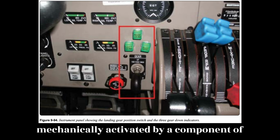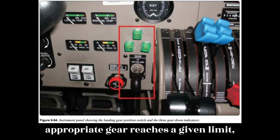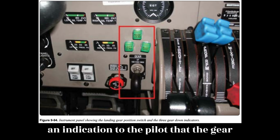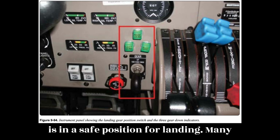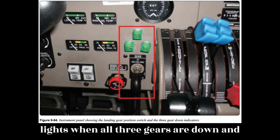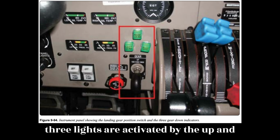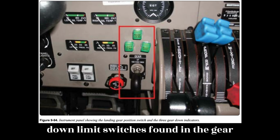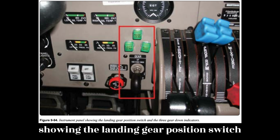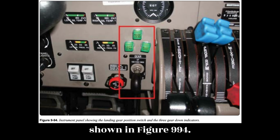Each of these switches is mechanically activated by a component of the landing gear assembly when the appropriate gear reaches a given limit. The landing gear system must also provide an indication to the pilot that the gear is in a safe position for landing. Many aircraft employ a series of 3 green lights when all 3 gears are down and locked in the landing position. These 3 lights are activated by the up and down limit switches found in the gear wheel well. A typical instrument panel showing the landing gear position switch and the 3 gears down indicators is shown in Figure 9.94.